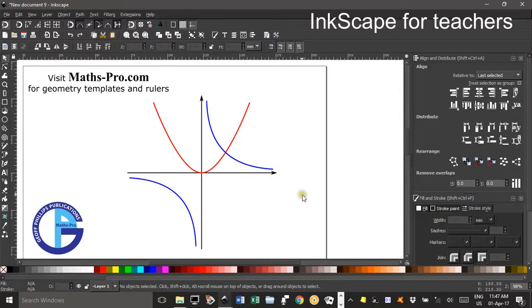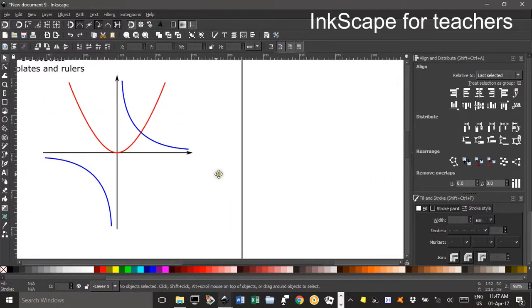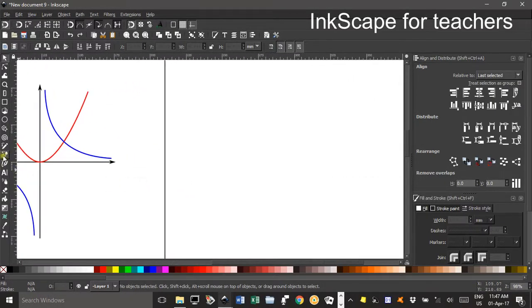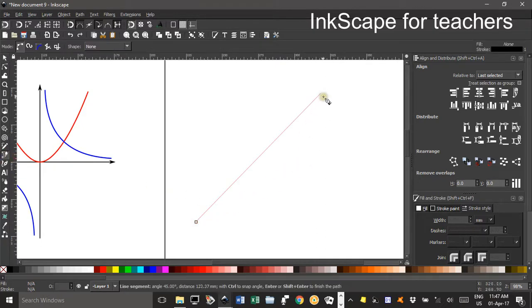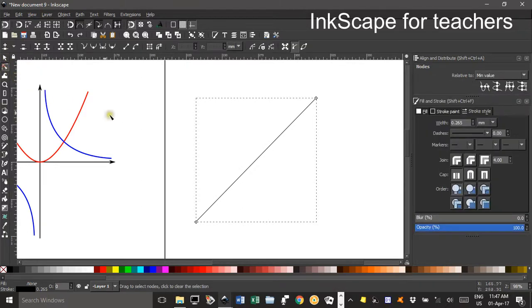To form something like a cubic function, you can start with a Bezier pen, click, Control, double click, and put in some extra nodes before I start trying to bend it with the nodes tool. So I click the nodes tool, then select one node, shift click to select the other, and select add a node. I might do that again, and it adds nodes in between.